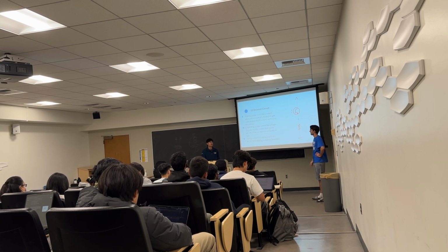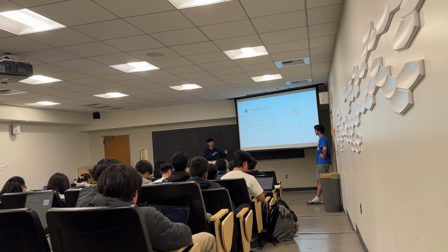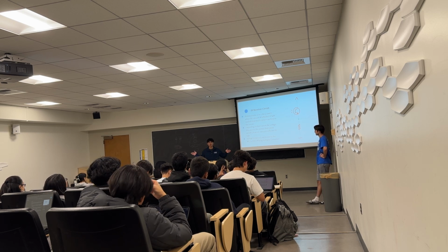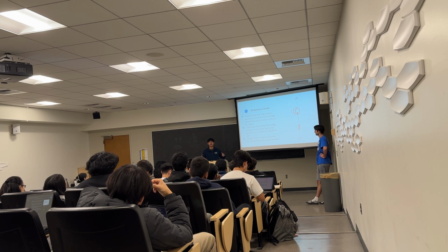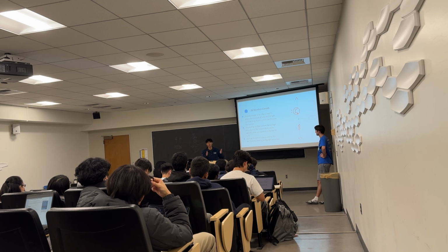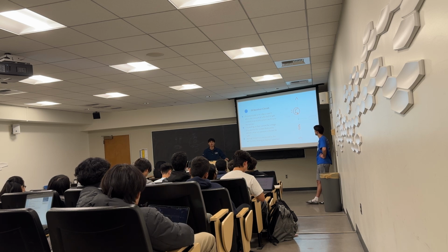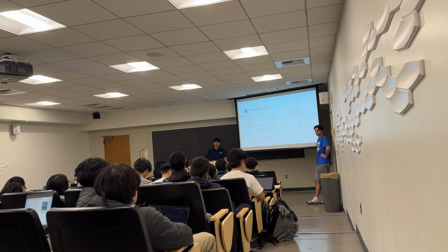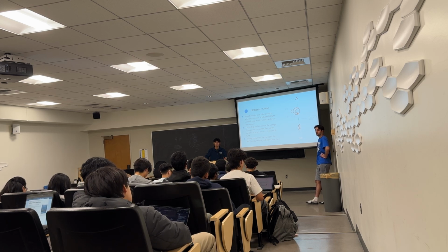I'm guessing based on the strength of this signal, that's how it handles it. It depends on what type of ADC you're using, the type it converts from voltage to actual digital values. Some can range from 0 to 1,000, or some can range from 0 to 100 probably. So just to clarify, you're getting analog values and you convert them to digital values. But don't you want analog values for your IR sensors in general?